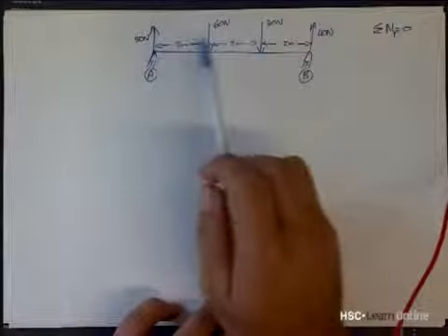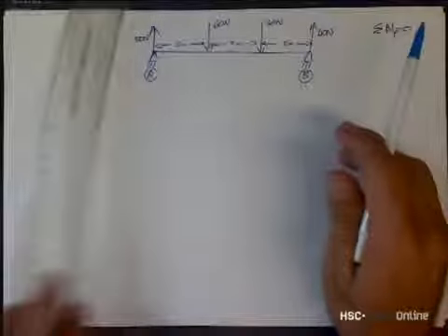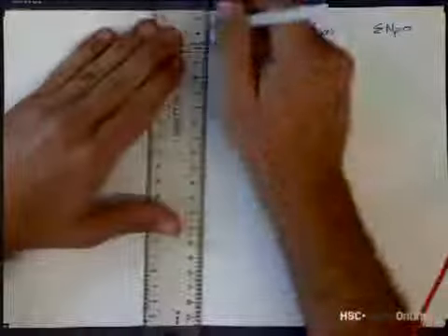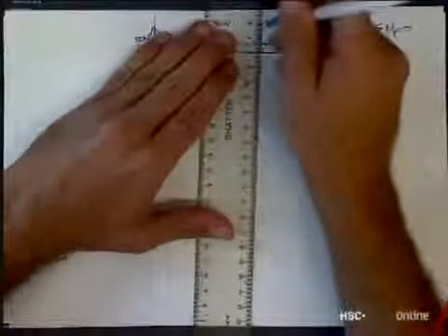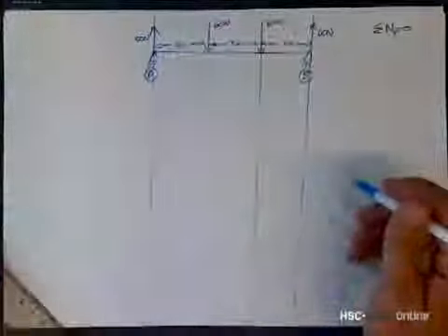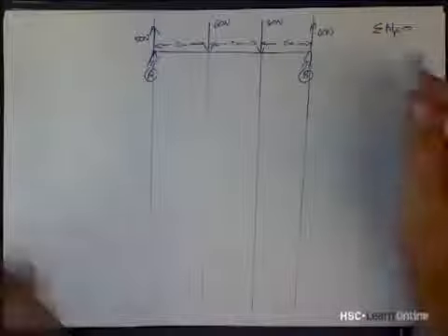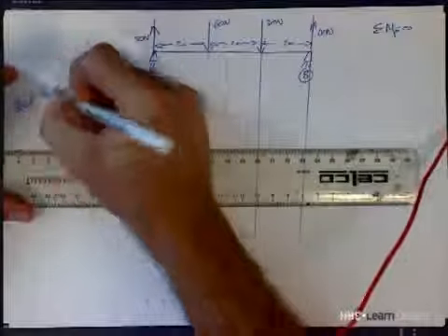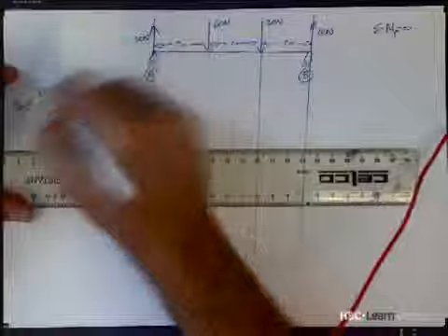But now that we have the three forces for our particular beam, we can go ahead and draw a vertical ruled line down each of the force lines. A force acts on a line. We're just drawing through these force lines so that we've got ruled lines down here, and we're going to do what's called a shear force diagram.